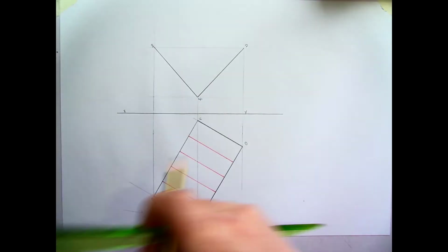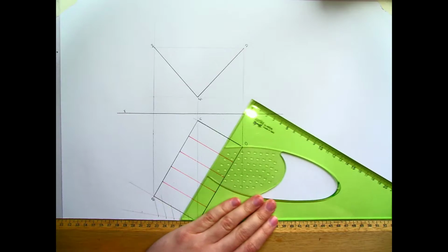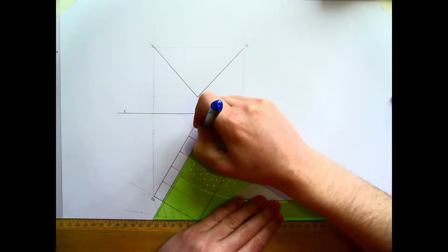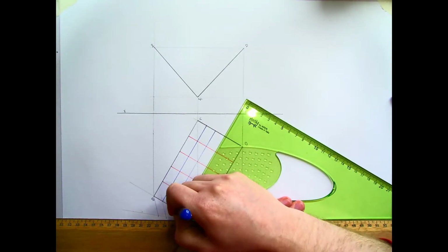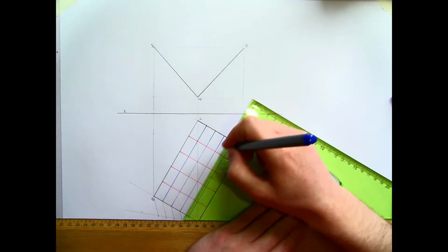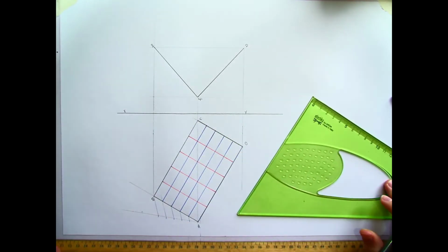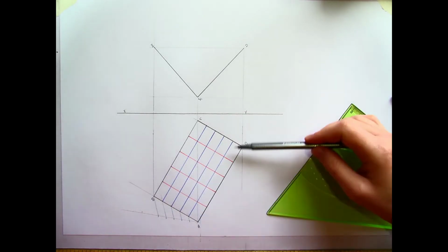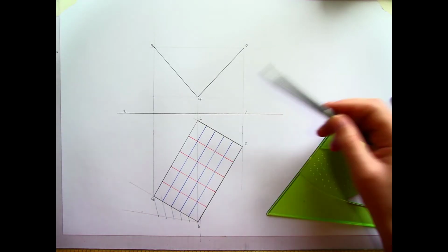So again, these lines are drawn at the 60 degrees, so it's based on a rectangle, so the ones on this side are going to be the same. So they've just got drawn at the 60 degrees. If it wasn't based on a rectangle and these were different sizes, we'd need to divide up both sides and then draw lines joining the two between. So there I have my elements drawn in plan for the line AD and BC, they're the red ones, and for the lines AB and DC, they're the blue ones.